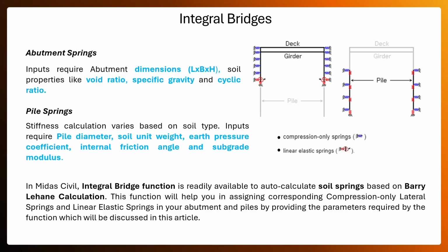So with these parameters as inputs for the abutments, the springs generated are compression-only lateral springs, since these are acting in the lateral direction, and these are acting as the lateral earth pressure on the abutments. And in case of piles, the linear elastic springs are developed.